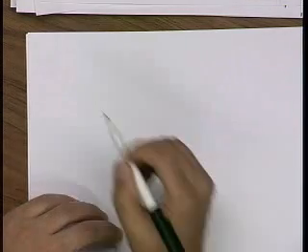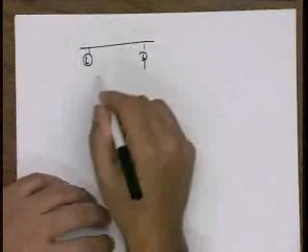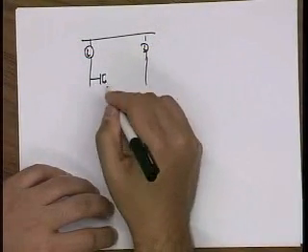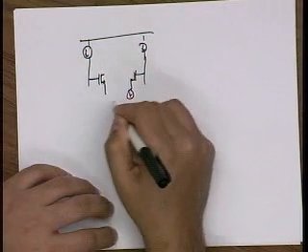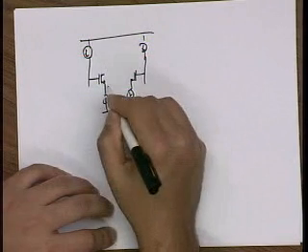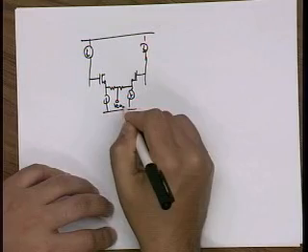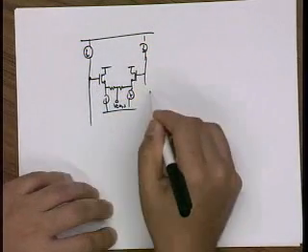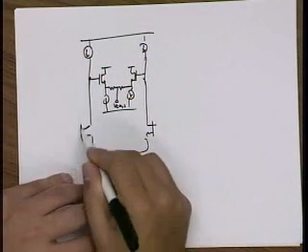Looks like you need a buffer. Yeah, why not? This is the business we're in. We're all circuit designers. All we do is move impedances around. So, okay, the output impedance is too high, so I'll buffer it. And now, this is my common mode sense. Is this going to work?